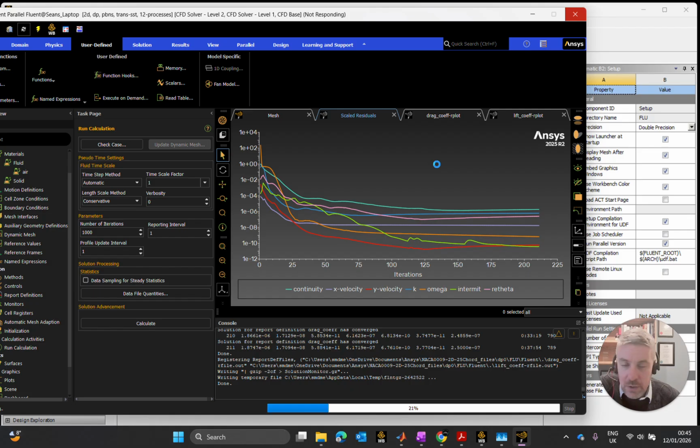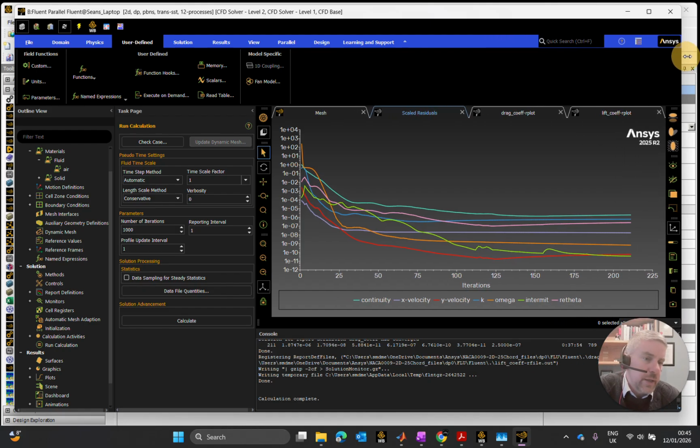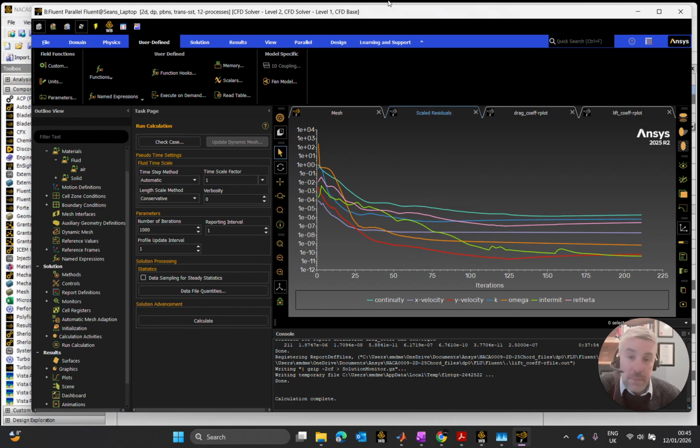It doesn't publish the drag, so we can't really look at that paper for it, but there are another couple of papers that I have found, which do give indications of drag, whether explicitly or by the L/D metric. So it'll actually be a nice one to do. We might write ourselves up here and name the expression, or even a function, and create a new variable in L/D and see how that compares itself. L/D is a nice metric to measure an airfoil's performance for a given Reynolds number and angle of attack.